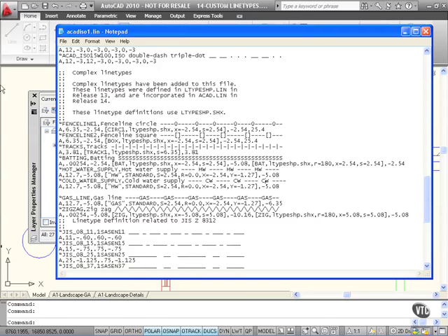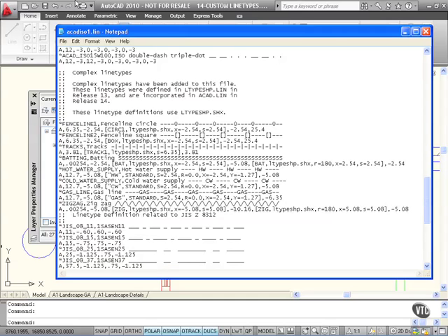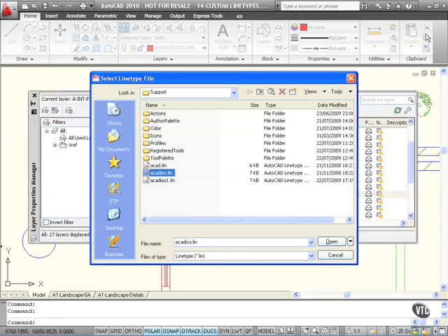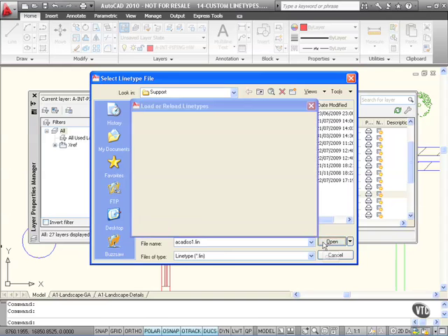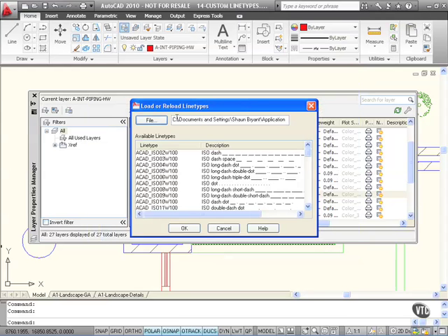So there's the CWs there, and then in the line here where it forms the line type, we've got HW there. So that needs to be changed to CW. Everything else is fine. So we'll lose that space there by hitting delete. Then we do a file and a save. And then I'm going to close that. And you'll notice now, look, acadiso1.lin. So if I select that one and click on open, it's using that file now.